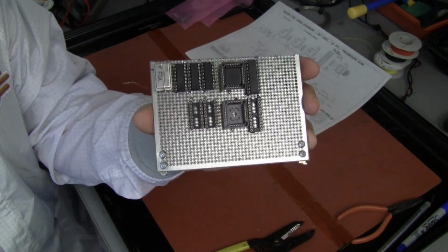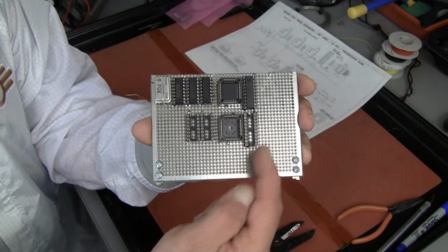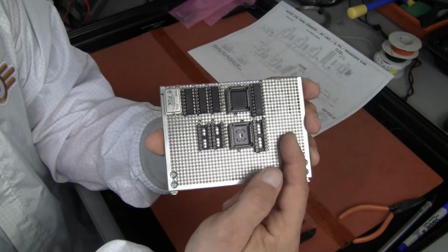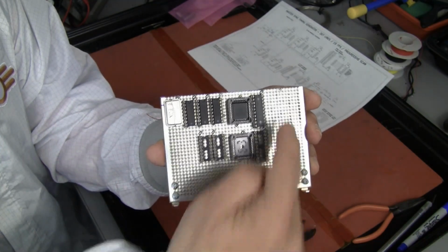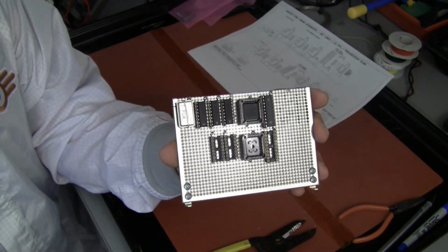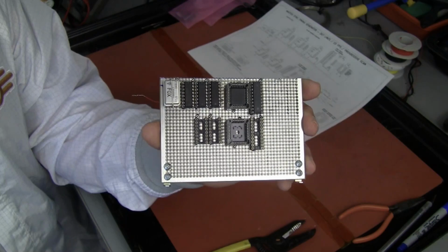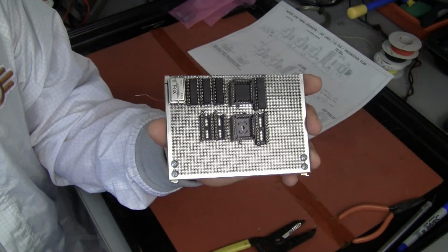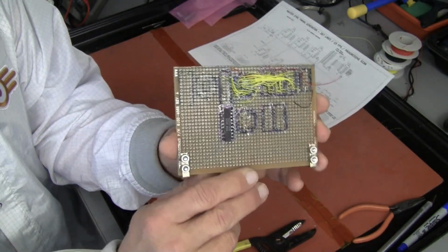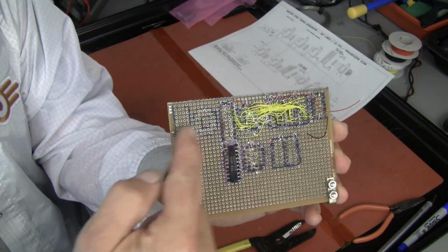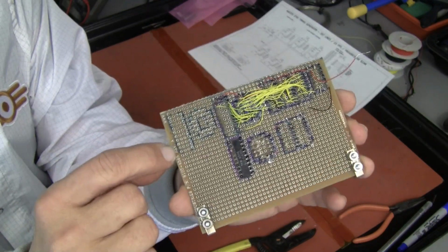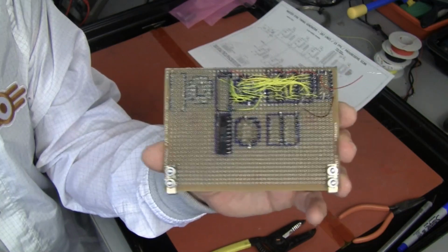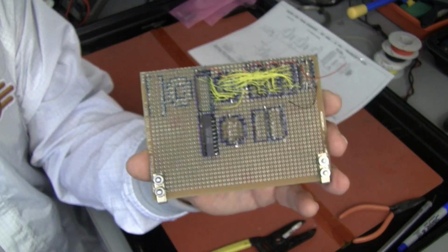So this is the board so far. The D to A converter chip will go here, and the op-amp chip will go here for producing the video. I believe I'm going to put a 5-volt regulator in that corner because the board will require plus and minus 12 volts for the op-amp. So this is pretty much 88% of the hardware that will be on here already. You can see I removed the wiring, of course, that went over to these other chips. It's like having a tattoo removed, there's a bit of a leftover image of the original position of those. So let's hook up the power to it and look at the pulses on the scope.